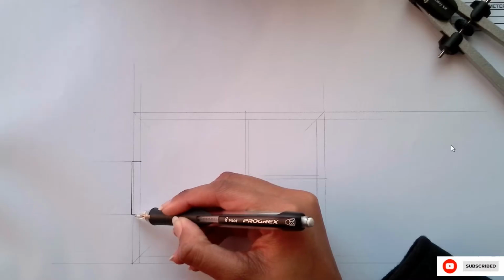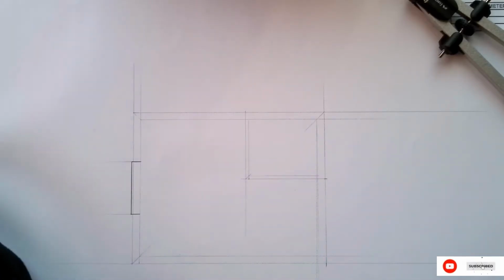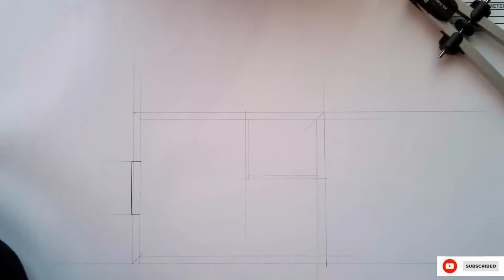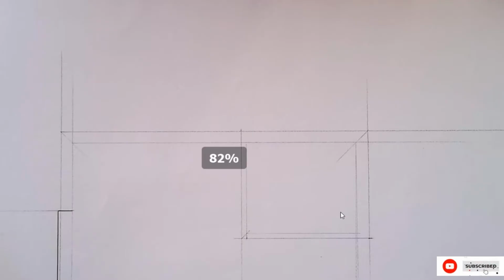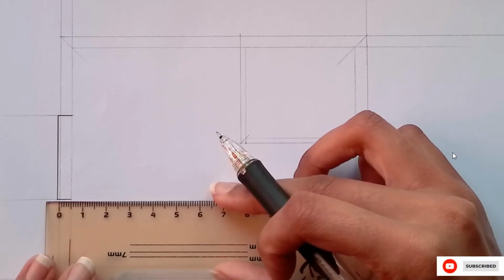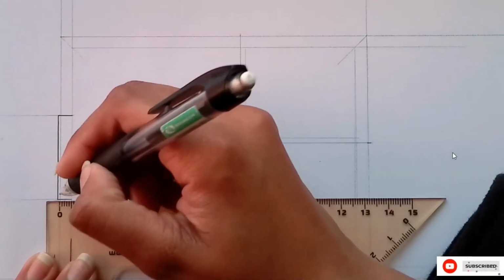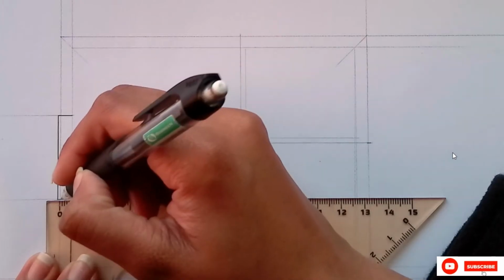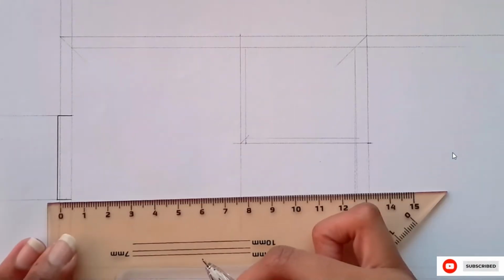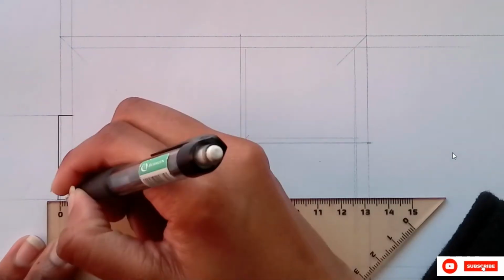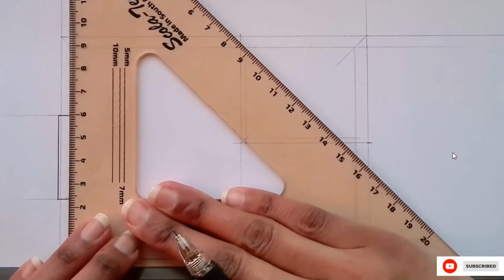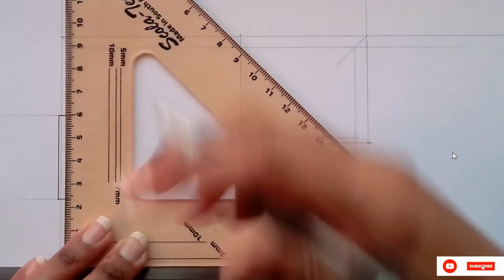So remember, for the frame, you have to use the wall thickness. So let me just zoom in. We want to focus here. Your wall was 4, so here I used 4. Then I'm going to measure half of that wall. From where that half is, you're going to go 0,5 out on each side.